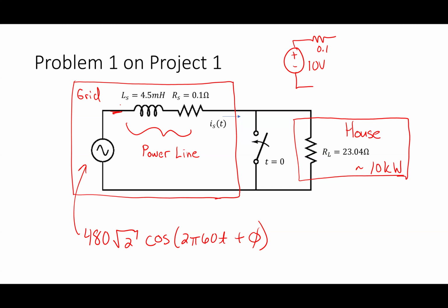What matters, probably? In the example I just gave, if I have a short circuit here, I'm going to get 100 amps that flows. How would I choose a circuit breaker? What would be the key thing I would need to know? How much load is on the circuit? Yeah, so if normally the circuit is expected to provide 20 amps, I know that if I'm providing 100, that's a lot more than I should be providing. So I probably want a breaker that's sized a little bit above that 20 amps. That's how we choose these things.